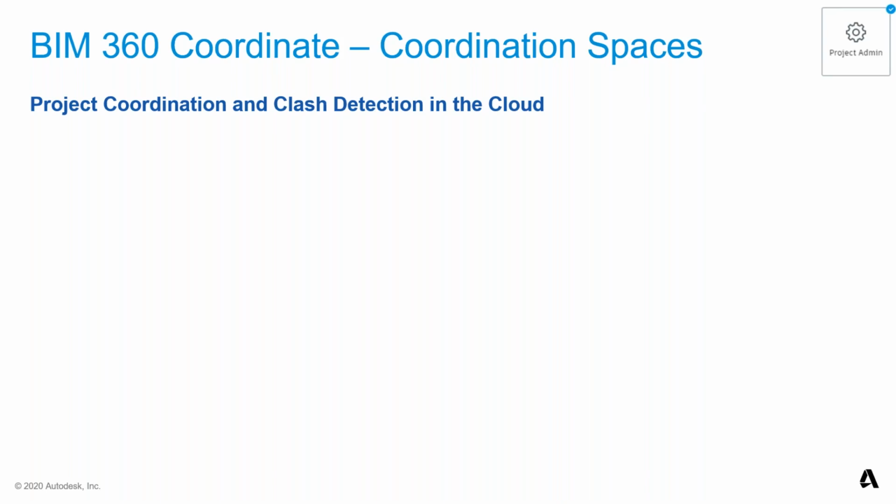In the case of Revit, you can also publish various views based on one model, and let these views clash against each other and against the Plant 3D model. For example, different disciplines will result in different views published from Revit, while in Plant 3D you split the project into various files anyway.